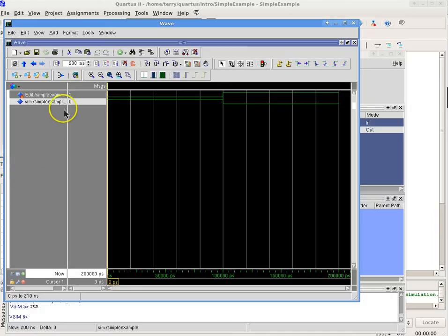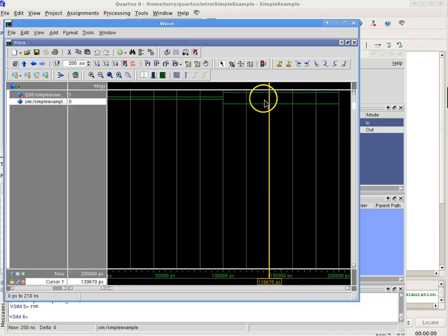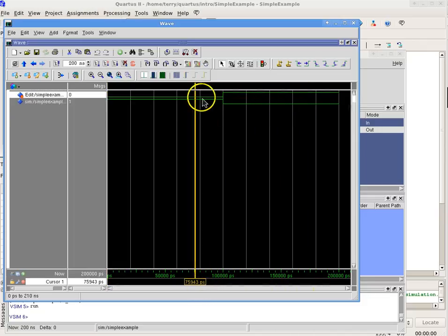You should see the inputs that you entered and the outputs from your system on the waveform. The period of the run will correspond to the time in the period window. All of the signals should be green. If any signals are red, then one or more of the inputs were not specified.